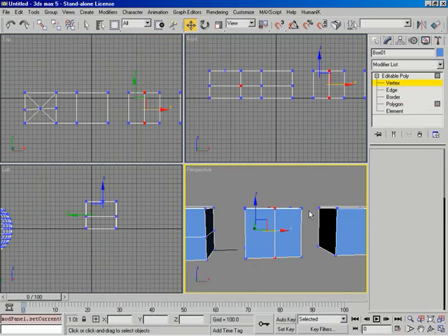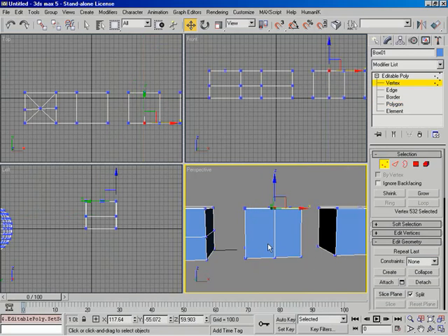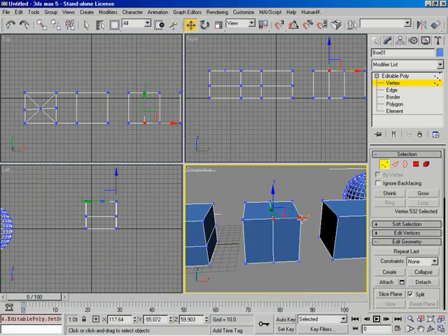and let's check this out by coming back up here in the vertex and grabbing one of these vertices and pulling. And we've got a slice. Be careful. If you pull the wrong way, it's going to look like there was a polygon magically added. No, that's not quite the case. It is actually an incision.